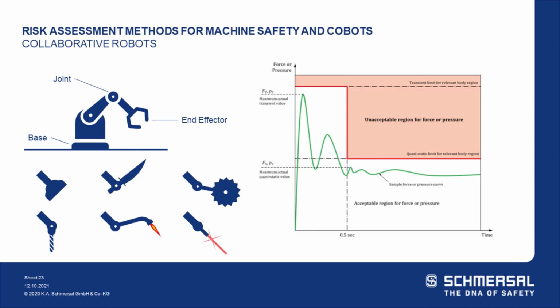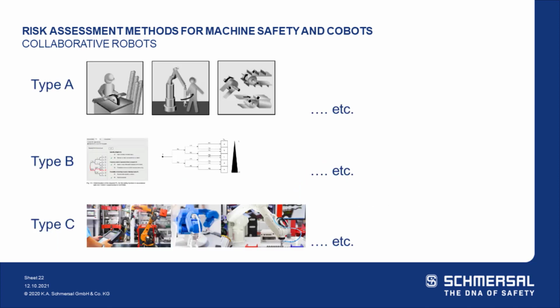Yeah. Another question, I'll read it from one of the audience members. I was under the understanding that a Type B standard applies to all machines. A Type C standard has usually been generated by a specific industry association, for example, and these standards supersede a Type B standard for that specific piece of equipment. Is that understanding correct? That is correct, yes.